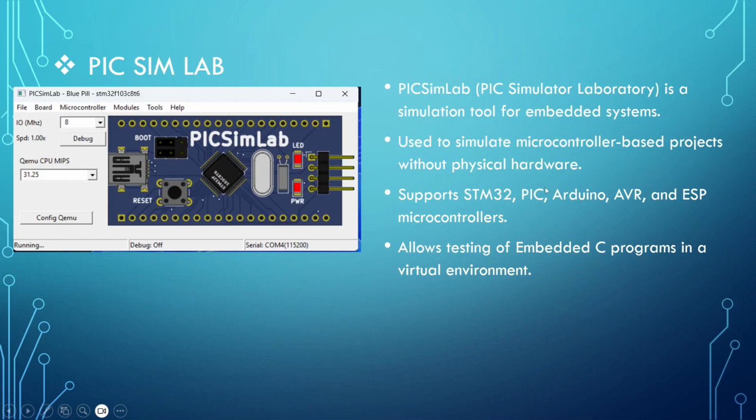It is a view of Proteus Lab. In Proteus Lab, we first go to File, then load binary file, then go to the files, select our file, and click OK. It will show our menu of what is happening in our code, and allows testing embedded C programs. And then move to our project.